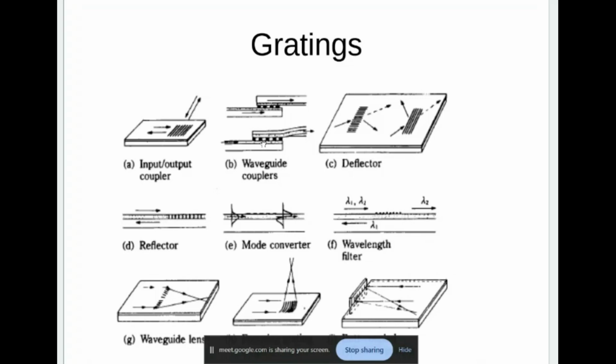The silicon people are not happy with that. See, these VLSI people, they want square type of devices. Like the Intel chip, if you see, it is a square. You can use all the space very optimally. Whereas if I want to have a small directional coupler, suppose you take this as the chip, from this end to that end is the coupler length, and the width is only small, this blackish region. Thin and long, the aspect ratio is very long. So we cannot make it, particularly if you want to cascade, it will require a lot more length. So silicon people are not happy.